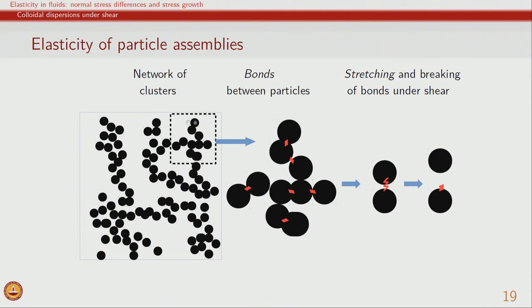And so, therefore, we generally have in these viscoelastic materials what is called stress growth. Stress growth is usually observed during either a simple shear flow or an extensional flow. Again the idea is to apply constant strain rate and then look at stress as a function of time. And by looking at stress growth, we can get an idea about what the elastic contributions within the material are, and therefore, we can again make a hypothesis regarding which mechanisms are important in determining the viscoelastic response of these materials.